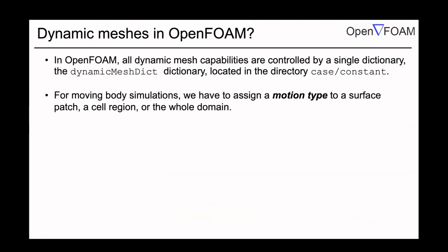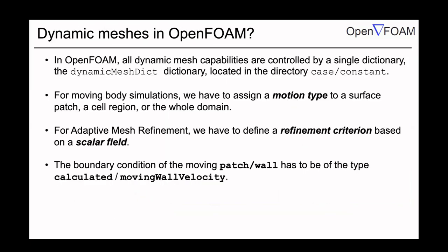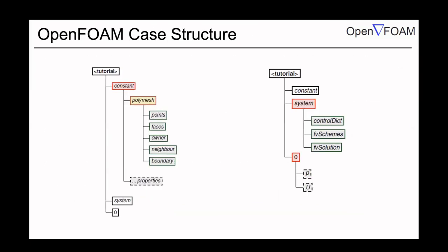All right. So I will quickly go through it. So this is not very important. The important thing is this. Now that you have actually seen all the case structure, if you want to include this dynamic mesh motion or moving mesh strategy, the only dictionary file that you have to include in the constant folder is called dynamicMeshDict. Okay, where you have to use appropriate moving mesh libraries and all related codes, of course, which is already written. You don't have to write it from scratch unless you want to modify them.